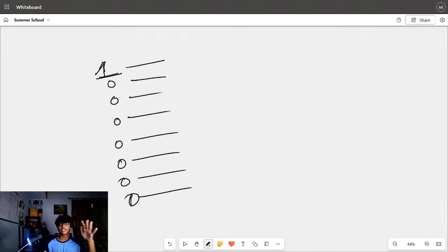So you can minimize the number of lines you use, because if you know one of these lines is 1, the others are redundant because you know that they're going to be 0. So instead of using 8, you can compress the information of which of the 8 is 1 into 3 lines. That's all you need. That is exactly what an encoder does.